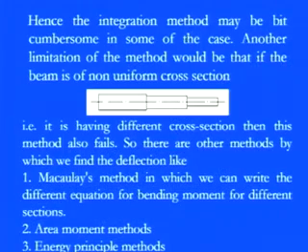But again, in both of the methods, the direct integration methods, in one form or other, there are certain discrepancies. Hence the integration method may be a bit cumbersome or bulky, because you need to describe all the expressions, for the slope, for deflection, or for shear forces. So in some way, you will find that we have bulky, cumbersome equations.